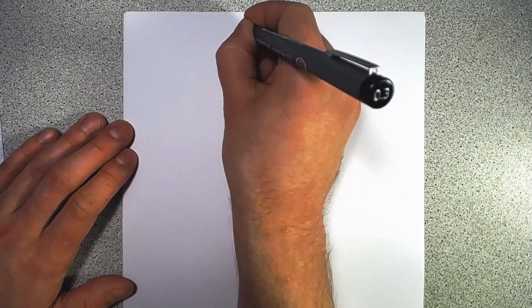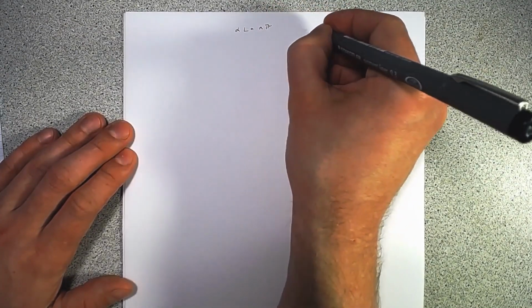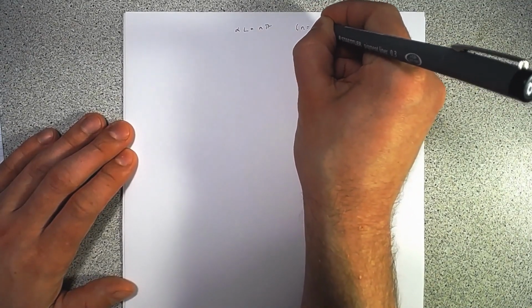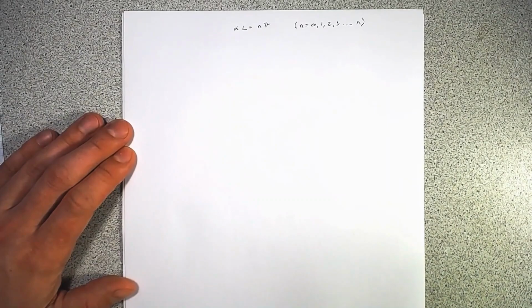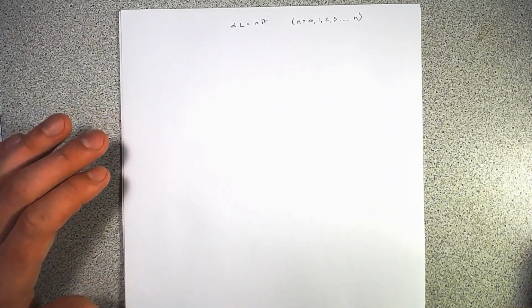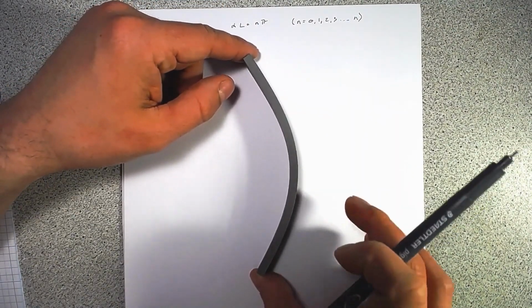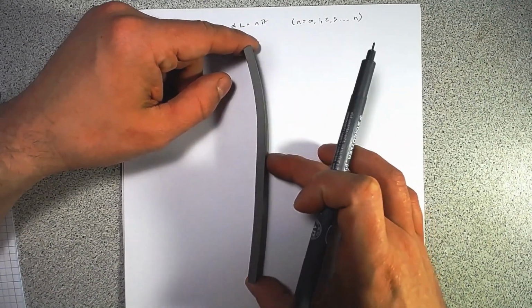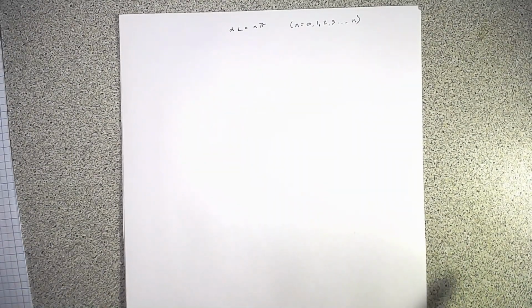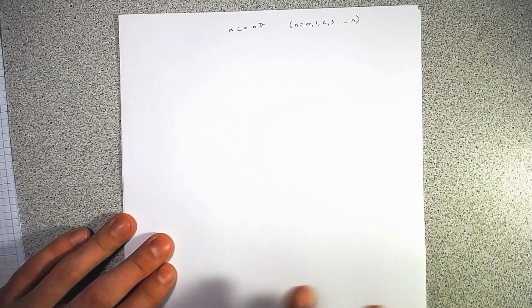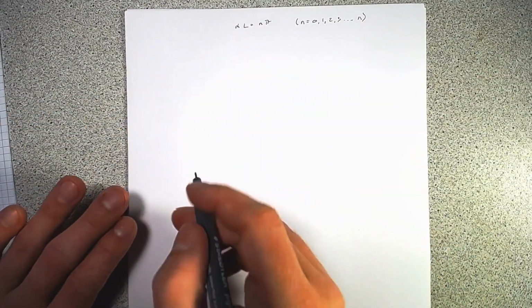So if we just repeat that up here, just so it's at the top of this page again: alpha L equals n times pi, and n equals 0, 1, 2, 3, all the way up. Well, that just means that we have this first buckling mode, which is n equals 1, or that's our second buckling mode, which is n equals 2, on up and on up. And so we're almost there for what our critical buckling load is. We're almost done with the math-heavy portion of the lecture, so just hang with us for just a second.